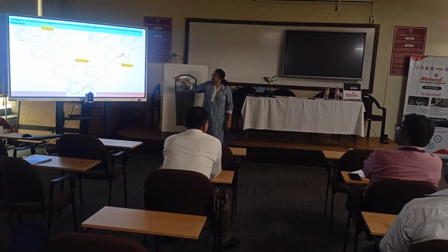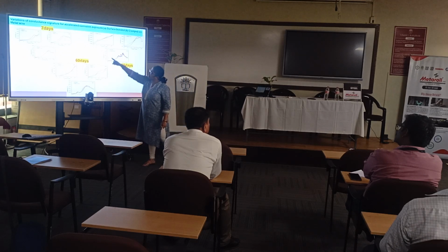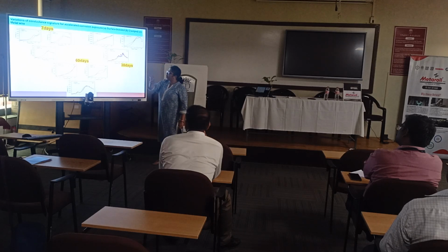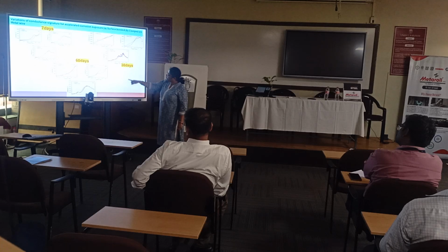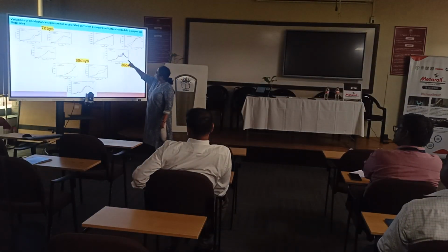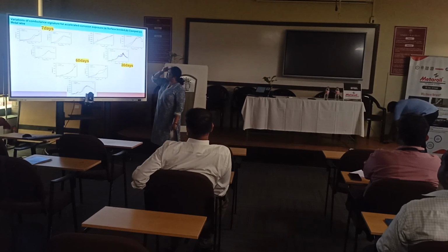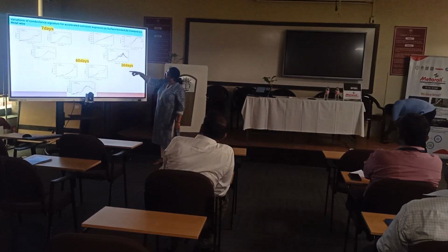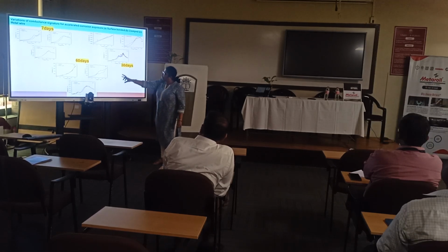Yes, sorry, this control one, if you see for 7 days, 30 days, 60 days, you have the baseline and the failure load test, because we know 40 kilonewton is the maximum failure load for the pull-out test. For the surface bonded, for the 30 days sample, something went wrong because it is completely corroded. But for the metal wire and clamp, the variation is very, very nominal.